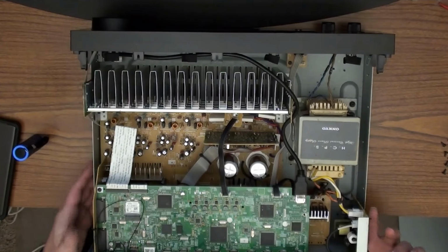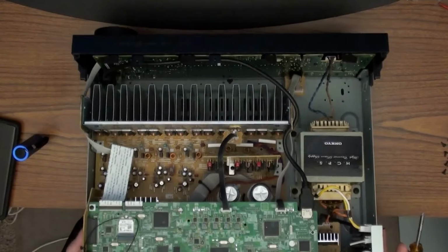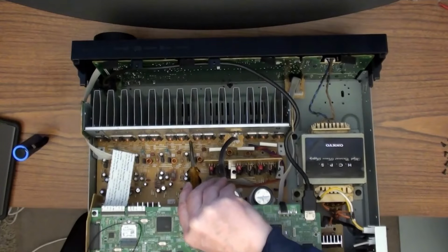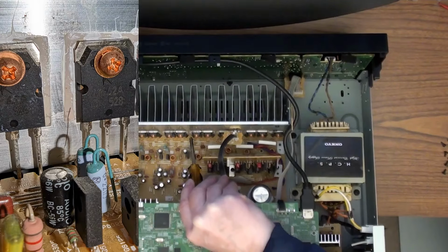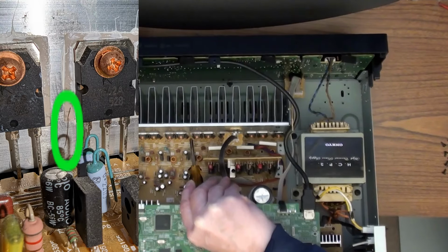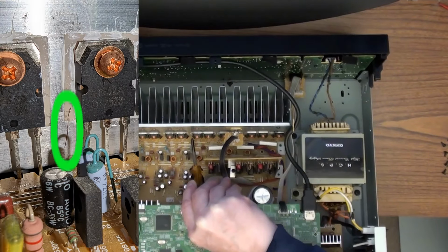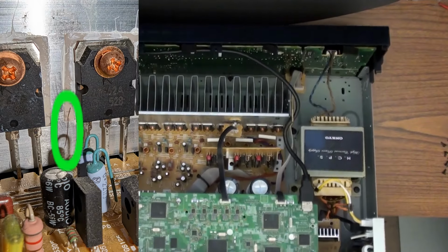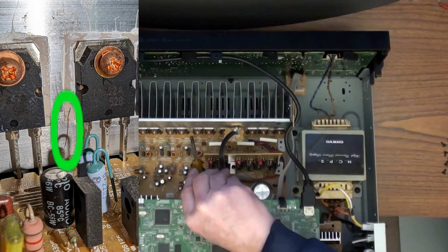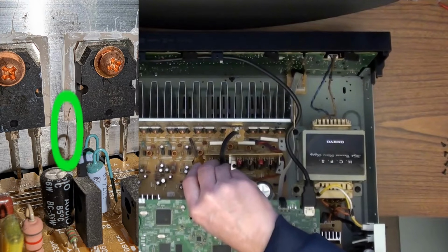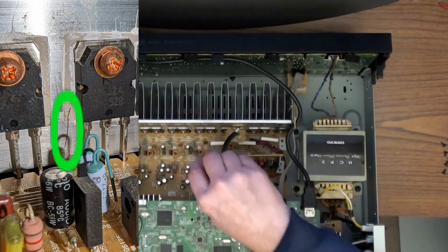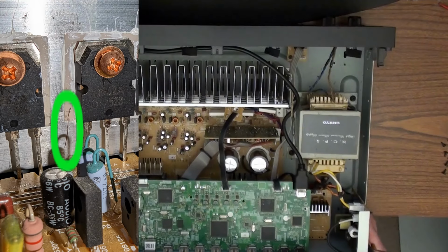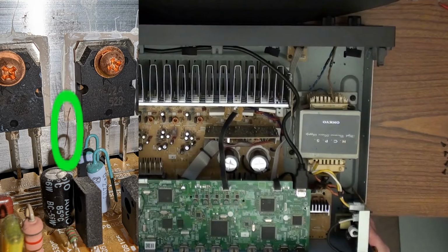So starting out, a real basic one that isn't a problem right now but could potentially be a problem is there's actually a wire hanging on the side in between these 2 transistors. It's just hanging there, caught on the white grease they have on there. I'll put a picture up for that one. If that one was to drop off and land on the circuit board, it could short 2 components together, and there goes your amp. So that's one.